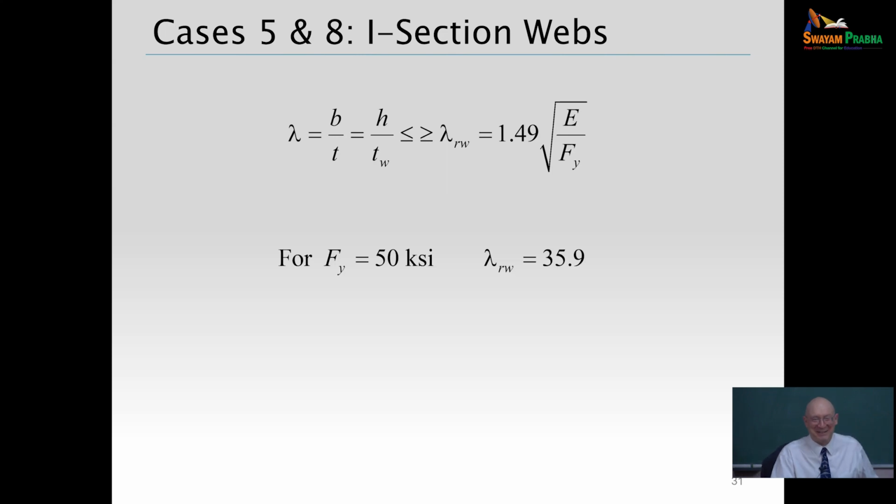Actually, in the new Indian code also this code came. Okay. Seismic design for steel structures. Okay. So in that code also we have two tables. Like Table, the D by TF based on this one. Okay. For ductile member, it will be reduced from like 13.5 to like 11 or 10. For the flange. Yeah. For the flanges. Okay. Very good. But if we just see that for plastic sections, it is coming around 7. Okay. D by TF. Okay. Here it is like in the first class. All right. Here we are only just separating slender, non-slender.